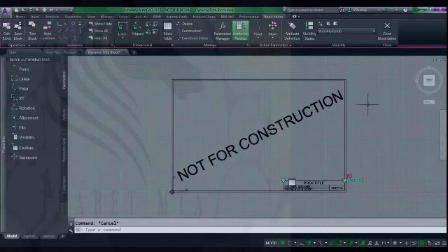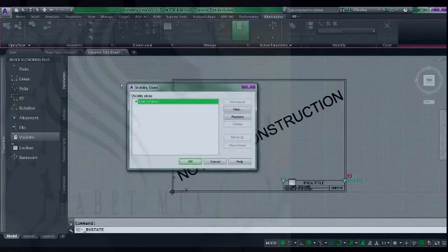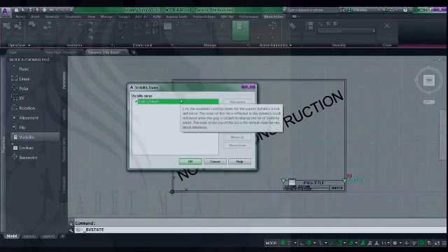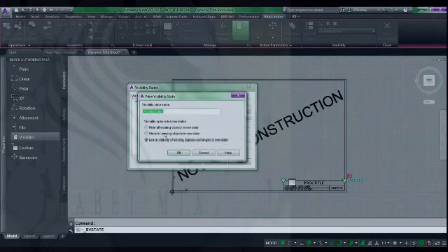Instead of adding an action, what this does is as soon as the parameter is added, I don't know if you noticed, here I'll delete this again. The visibility states panel is grayed out until you add that parameter. So I'll add the parameter in again, and there it is. So now this becomes available. I can click on the Visibility States Manager, and it opens up this dialog box and allows you to add new visibility states. So what I'm going to do is click New.